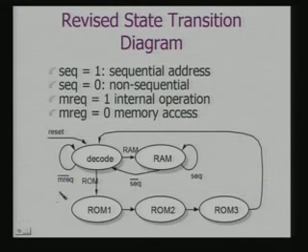So, effectively the finite state machine that defines a controller for the bus transaction would look something like this. Depending on whether it is sequential or not, I know that in this state I shall activate the CAS only case or RAS CAS, depending on the condition. Otherwise, when it is a ROM access, I have to go into a wait state, particularly when there is a memory request.